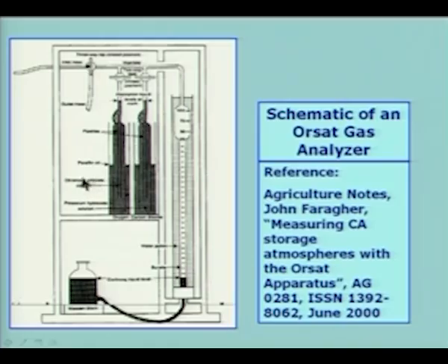The lettering here is not very clearly visible, but it does not matter, I will describe it as we go along. So, you see here there is a 3-way valve which can either connect to the atmosphere or to the source of the gas, and then there is an outlet also. Okay. So, it is a 3-way, that means one, it will connect to the atmosphere or to the gas which is being fed into the system which we are sampling, or it to the outlet, so that we can send it away out of the system.